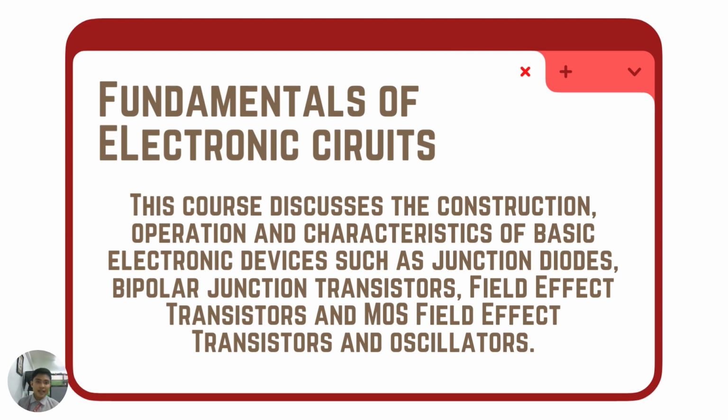In the MOS field effect transistor, we have what we call the metal oxide semiconductor. The primary use of a MOSFET is to control conductivity, or how much electricity can flow between its source and drain terminals, based on the amount of voltage applied to its gate terminal.